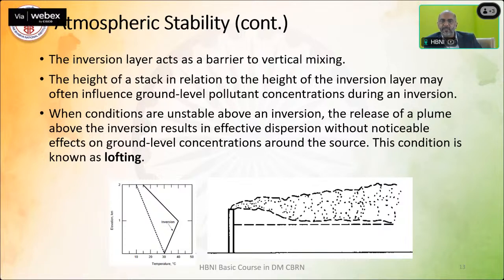It will be different for different sorts of inversion. The height of a stack in relation to the height of the inversion layer may often influence the ground level pollutant concentration during an inversion. If the stack height is above the inversion layer, it will not allow the pollutants to settle down. And if the height is lower, then it will be a different case.